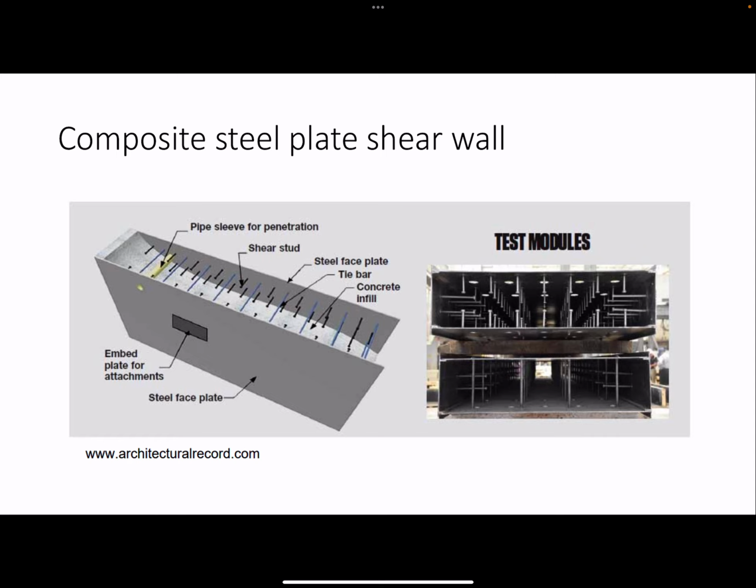So the beauty of this is that those steel plates are part of the permanent structure, and they also serve as the formwork. So it's a lot more efficient materially for the construction, and also big time with regards to labor and time, because you don't have to wait for that wall to cure before removing that formwork and using it for the next level.